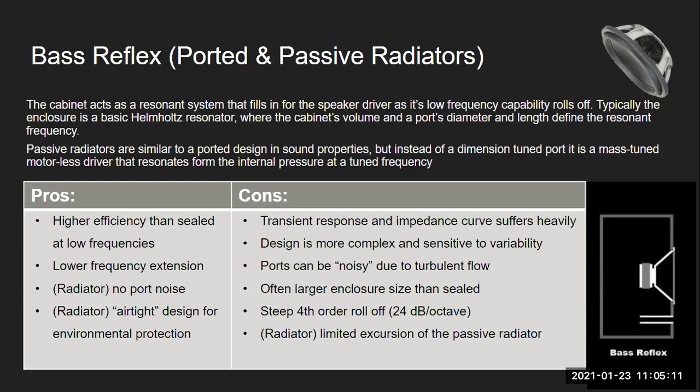If you think about blowing on a Coke bottle, it takes a second for that resonance to build. That's the way I've visualized it with a bass reflex design: it takes a second for the low frequency response to build in amplitude. So there's this temporal smear in the low frequencies, and that can result in that muddy bass sound. That's why a lot of audiophiles tend to say ported designs sound sloppy in the bass, which is typically true if you're a very critical listener.